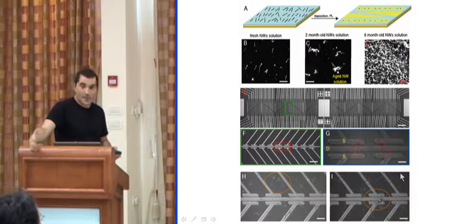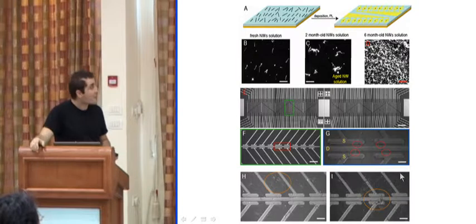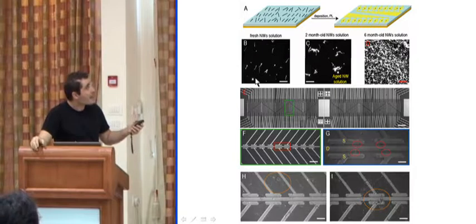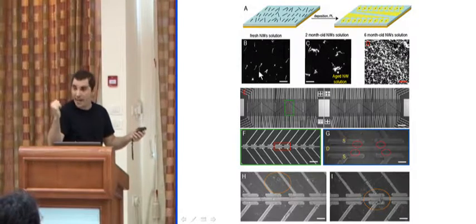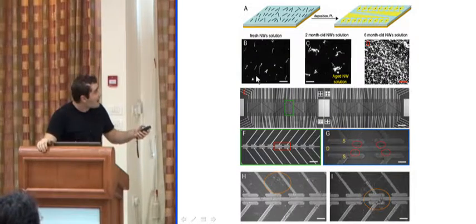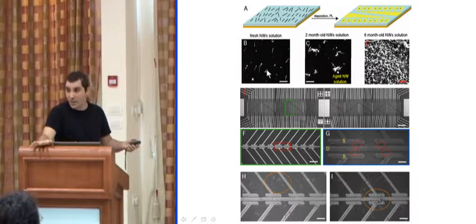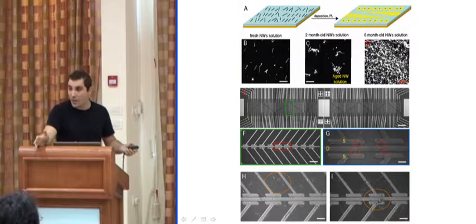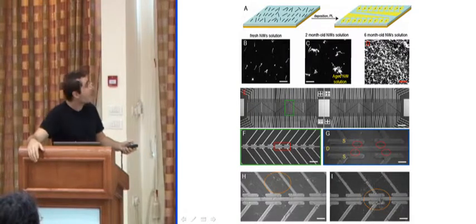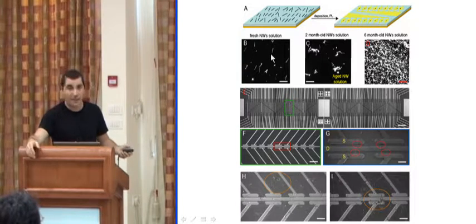What happens when the deposition, what I call the critical deposition approach, doesn't work. In many cases, when we deposit nanowires, we can see what we call flow alignment. Nanowires can be aligned to some extent, but we cannot control the places where the nanowires are. In many cases, the nanowires aggregate when the concentrations are too high. So definitely those two cases won't lead to any satisfactory or good device. In this case, the number of nanowires is so small on the surface that most of the devices won't have any nanowire in between the electrodes.